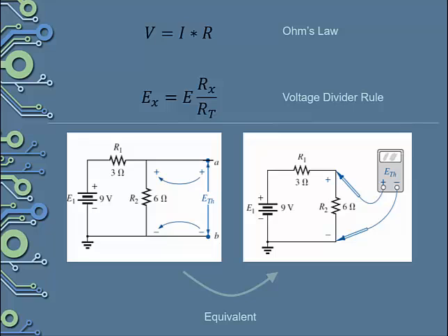From this, we can now calculate the Thevenin voltage, which is done by first returning all current and voltage sources to their original position, while still leaving the component between A and B out. The voltage across the points A and B can then be found through either voltage divider rule or Ohm's law. The voltage found from this is to then be used as the Thevenin voltage, or ETH. In the figure given, the voltage across points A and B will be the same as the voltage across the 6 ohm resistor and can be found from using the voltage divider rule.